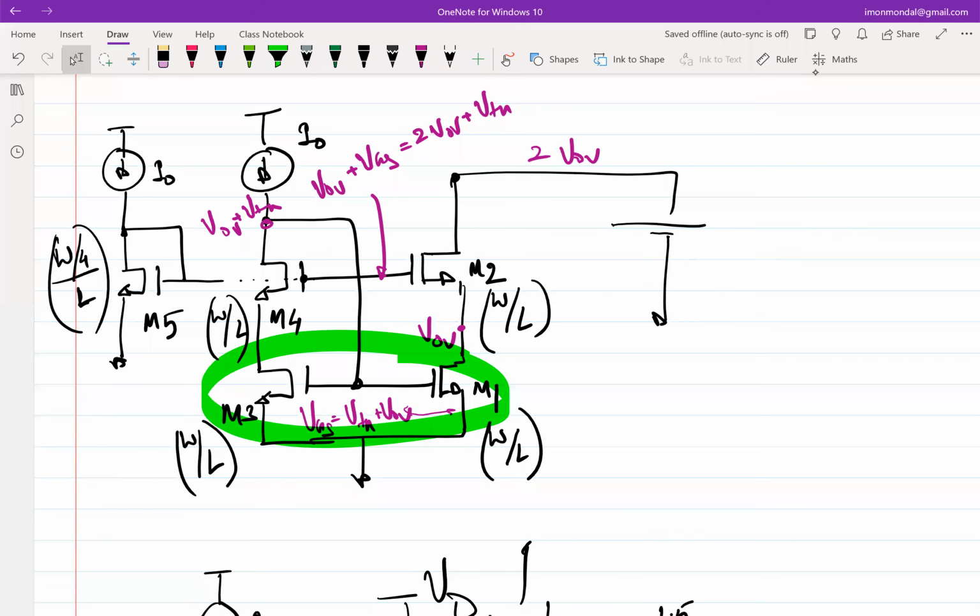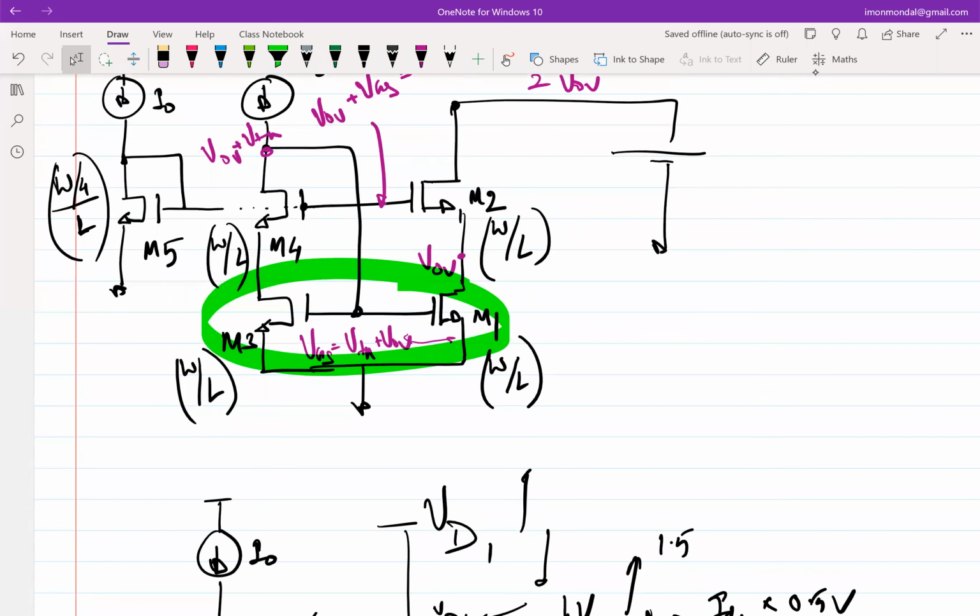So the purpose even of the simulation assignment is to show you how much change you have been able to suppress. So it's not perfectly 0, but it will reduce. So you have to theoretically calculate and also simulate and see how much it has reduced. So basically the slope will change, right? The ID-VD slope has to change in order to increase RDS, isn't it? So that's essentially the purpose of this assignment. Okay, fine. So let's move ahead.